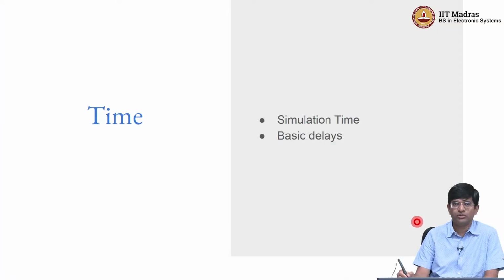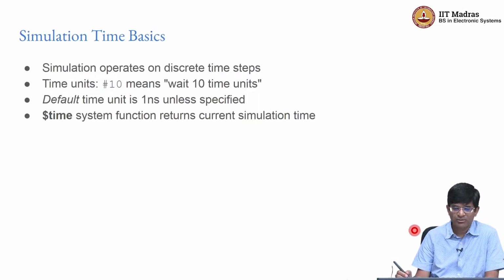Okay, so hopefully by now the point that time plays a very important part in Verilog simulations is clear. Let's spend some time trying to understand what exactly this notion of simulation time is and what these delays mean. Simulation operates on the notion of discrete time steps. Time as we understand it is an analog quantity, right?